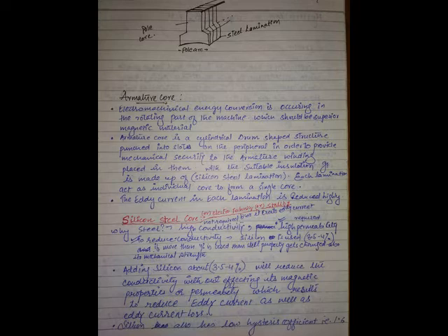Now, when 10 segments pass by a brush in 1 second, there is a chance of the spark spreading onto 5 or 6 segments, yes or no? When a spark spreads onto 3 or 4 segments, it is nothing but a short circuit inside the coils. Spark means a conducting ring, a conductor placed like this. So with a conductor like this, the coils corresponding to those segments will be short circuited. Short circuited means high current. Whenever there is a short circuit, it produces a high current.